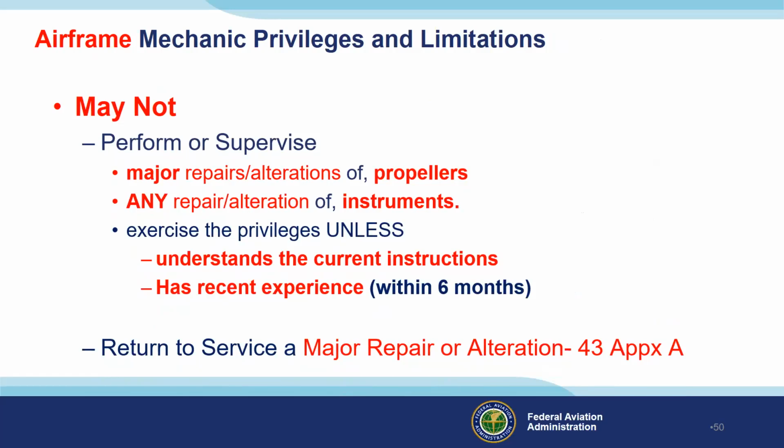Within 6 months, you have to have done that action. And you cannot return to service a major repair or alteration. Those are defined in Part 43, Appendix A.